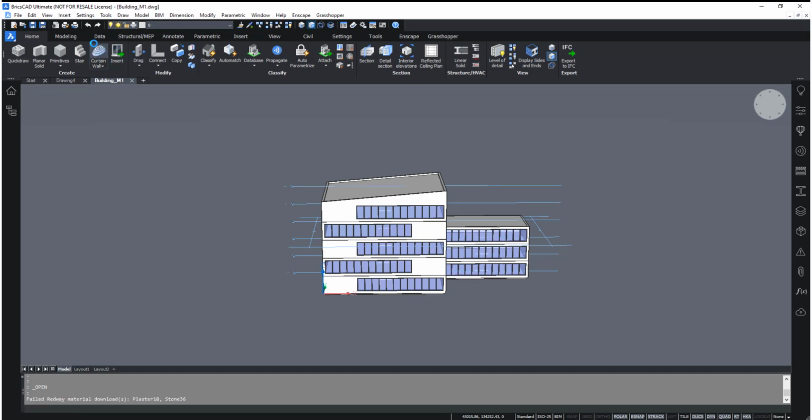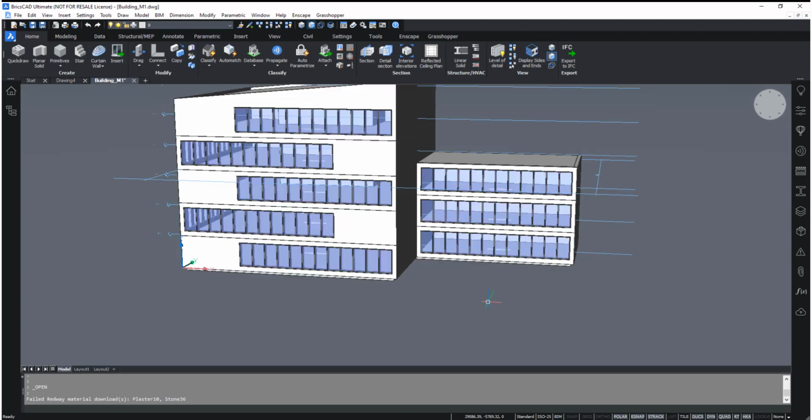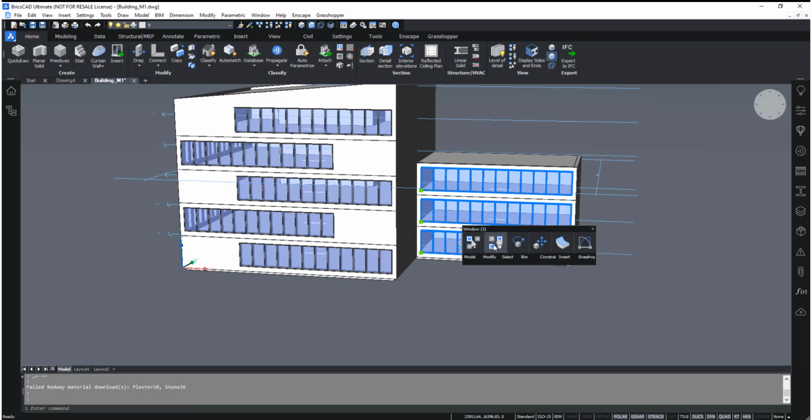The hide tool temporarily hides selected entities in the view. Now in this drawing, we want to hide the windows on the right side of the drawing. So go ahead and select the windows by left-clicking each of the rows, and you'll notice that our quad menu appears. Now mine shows isolate and hide entities on my quad menu. That's just because I've recently used that.